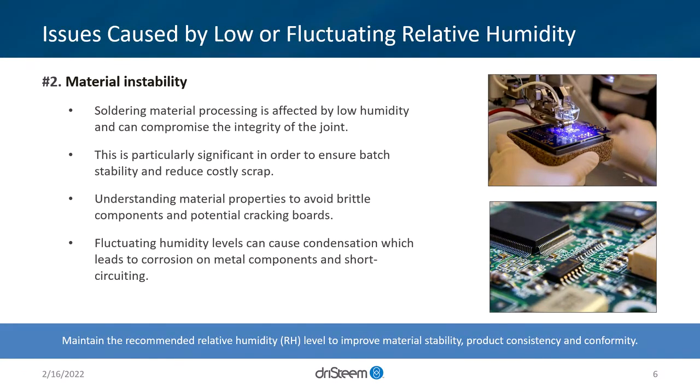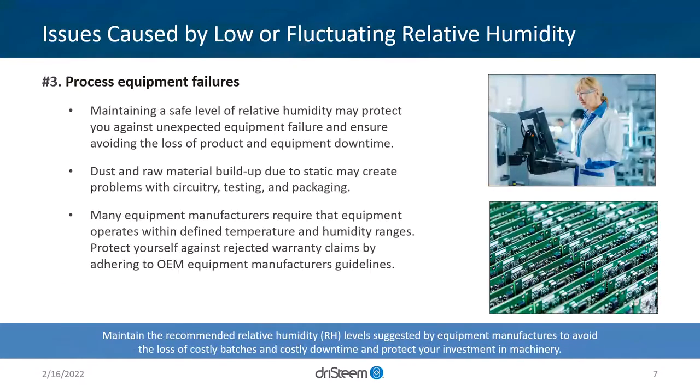So having that fluctuation, this really comes back to process control. If we're at steady state, we want to make sure that we are at steady state with RH, and temperature can influence that. If we fluctuate, we can cause damage to components from expansion and contraction. We want to do our best to mitigate that risk.